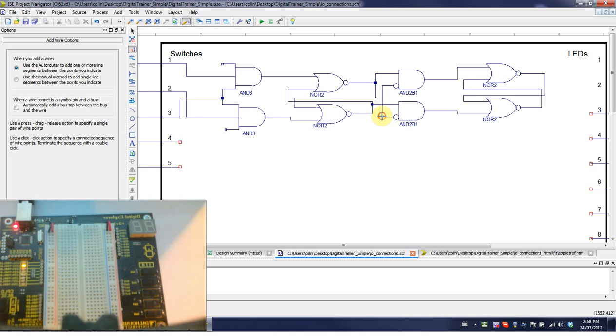So we can sort of see, when we talked in class about how we build flip-flops from two latches, one with an inverted clock. You can notice right here, we seem to have an RS latch, these two gates here. And we also formed an RS latch with these two gates. In this middle part, we have the two AND gates on the input, so that is what we showed as an enable pin. And same with the thing here, we have what is effectively an enable pin on the inputs.